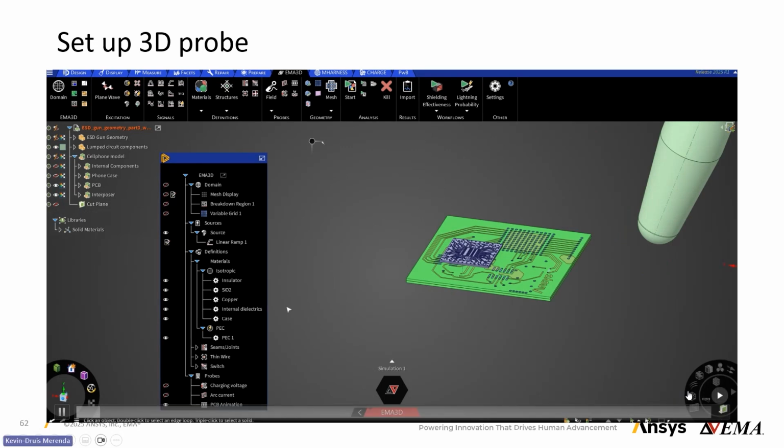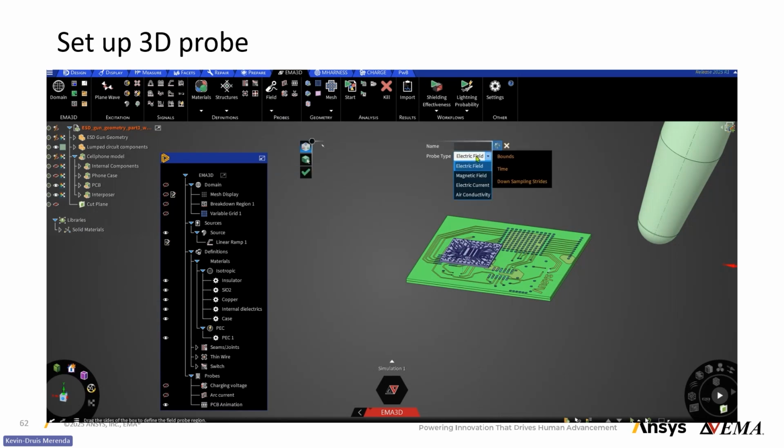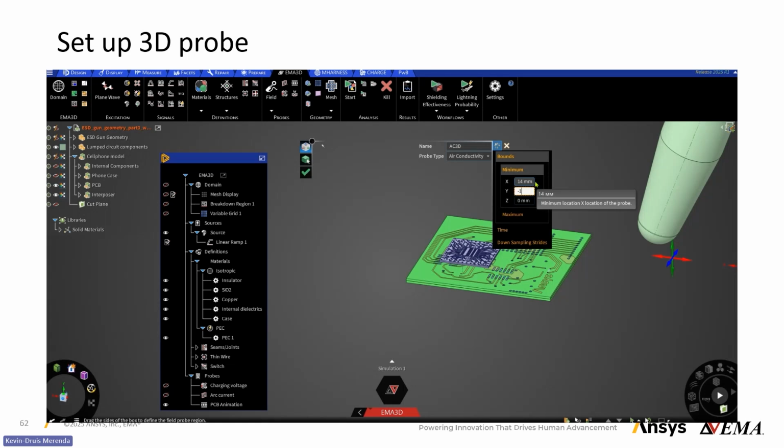And then we'll still do a 3D probe because, again, our goal is to track down the location of secondary ionization in the system. If you were to open the device up after you do this test, you could get some damage inside the system. That's how you would understand that there is secondary arcing happening. Or you could get a short or a spark that will trigger one of your sensitive components, and maybe kill signal in some way down the line. So to understand any interference from a spark, you need to know where they occur, so that you can mitigate them by either changing the placement of the PCB or adding some diodes in the system, for example, or changing some of the component parameters.